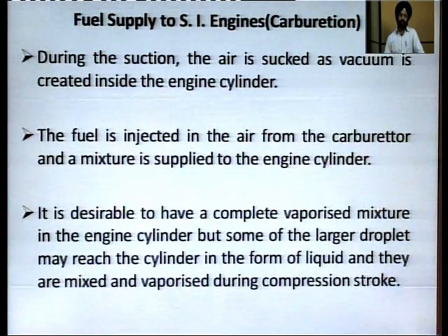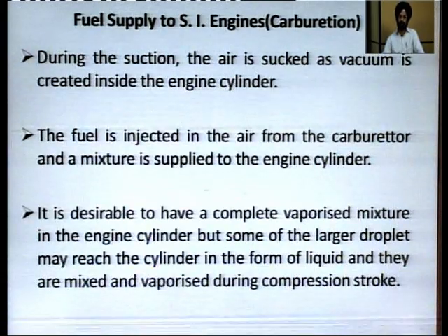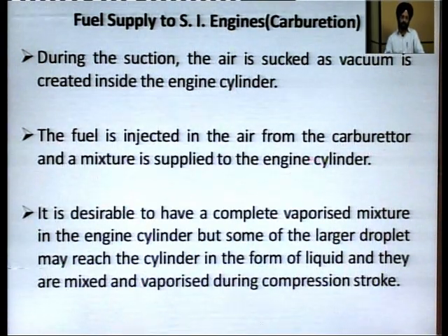During the suction stroke, the air is sucked in as a vacuum is created. This air is sucked into the carburetor, not directly into the engine. So, during the suction stroke, the air from the atmosphere is sucked into the carburetor, and the fuel is injected into the air by the carburetor, and the mixture is then supplied to the engine cylinder.